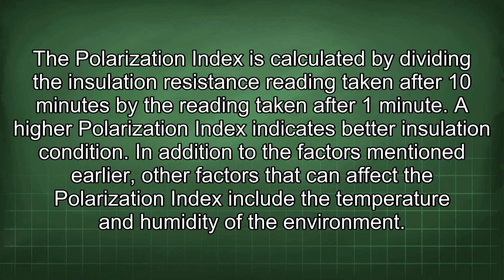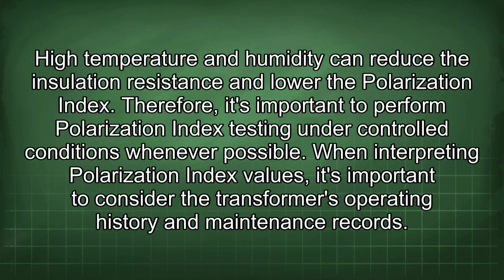In addition to the factors mentioned earlier, other factors that can affect the polarization index include the temperature and humidity of the environment. High temperature and humidity can reduce the insulation resistance and lower the polarization index. Therefore, it's important to perform polarization index testing under controlled conditions whenever possible.